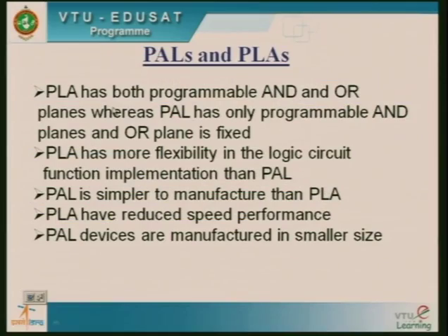PLA has both programmable AND and OR planes, whereas PAL has only a programmable AND plane and the OR plane is fixed. So in PLA, I can program both the AND planes and OR planes.